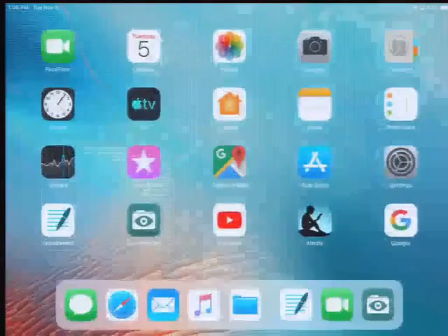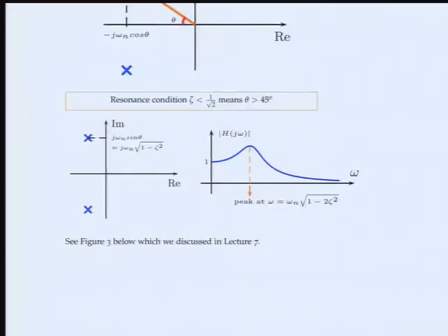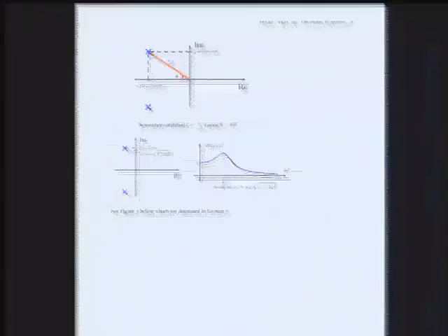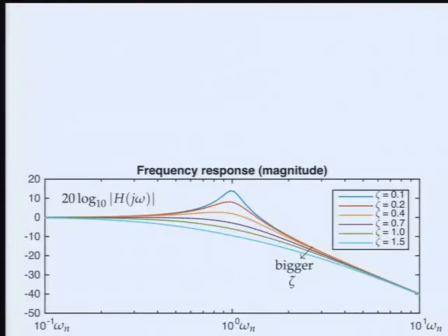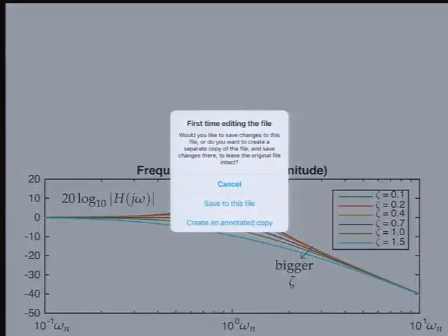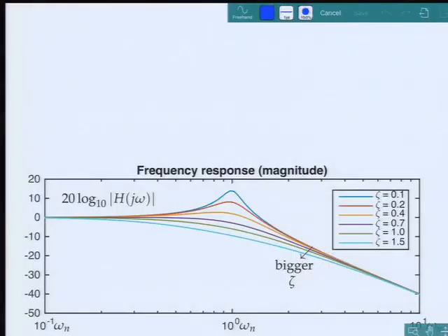So in the last lecture, we had some Bode plots, I mean, the frequency response plots for this second order term, and they look like this. Okay? Our Bode approximation here is basically a straight line approximation to this, no matter what the actual zeta is. So it looks like that, constant, and then it goes linearly down. So this would be our Bode plot, and obviously it would miss all that stuff if zeta is small. All right?